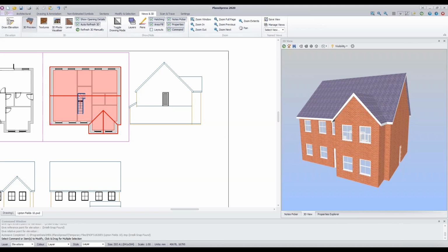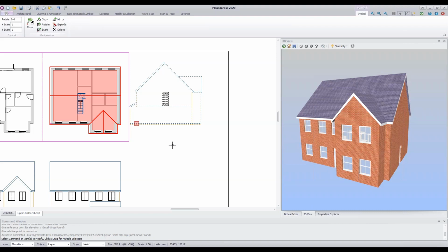So this is one of those times where, because I clicked my depth of the elevation beyond the building, it's actually included this utility door because I've gone all the way through to the other side of the building. So again, I need to do a little bit of playing around, a little bit of editing of this elevation. Alternatively, I could redraw it and not include that far wall in the elevation. In fact, I'm going to do that. I'm going to redraw it this time.